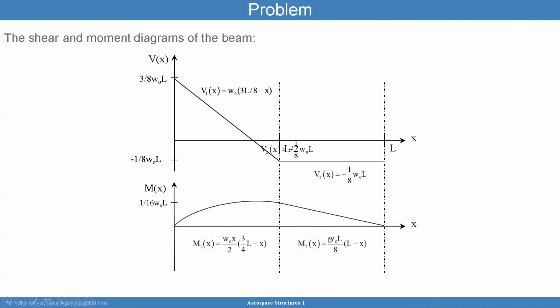and bending moment diagram. Note you can also construct this bending moment diagram by integrating the shear diagram. You can see here there's a straight line, so the derivative of this straight line gives you a constant, or the integral of a constant gives you a straight line. And then there's a quadratic shape because this shear is a function of x. And so you can integrate that to get a quadratic shape.